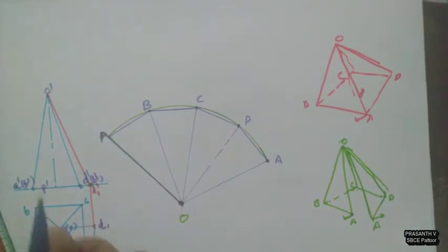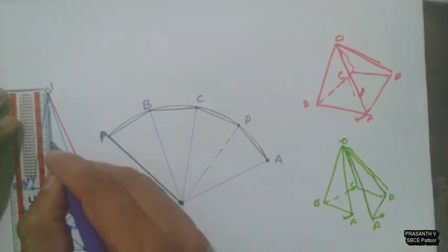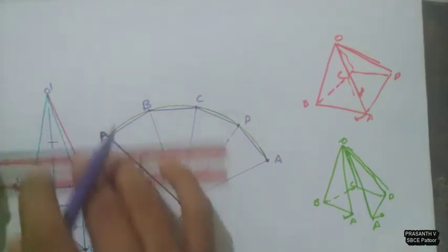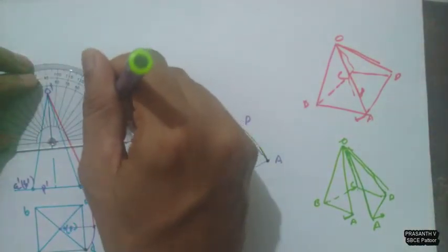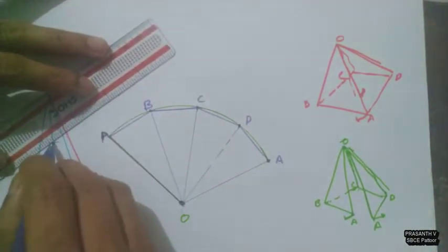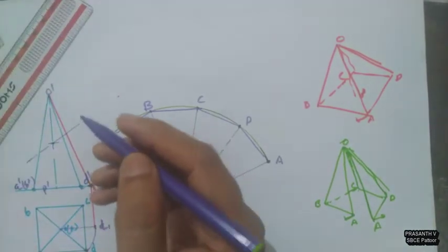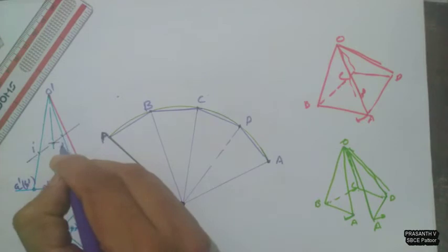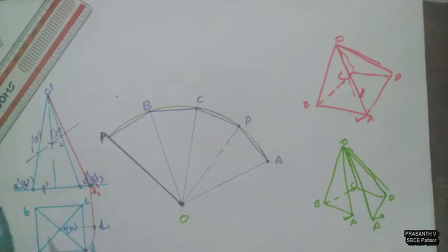Now we can consider the section plane also. The square pyramid is cut by a section plane which is inclined at an angle of 30 degrees through the midpoint of the axis. Here you can see the points 1 dash, this is 2, again 3, here it is 4. So that you have got 4 cutting points.